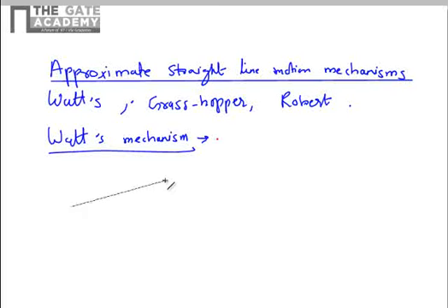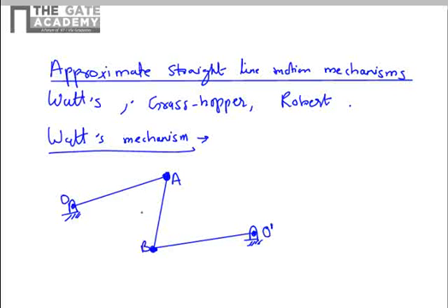So it is basically formed from three main links. It is also a 4-bar chain, but the fourth link is fixed. So a 3-link chain. This is anchored to the ground. This is one rotary joint. This is another rotary joint. And this is a third anchored to the ground. So this point we will term O, this A, this B, and this may be O dash.